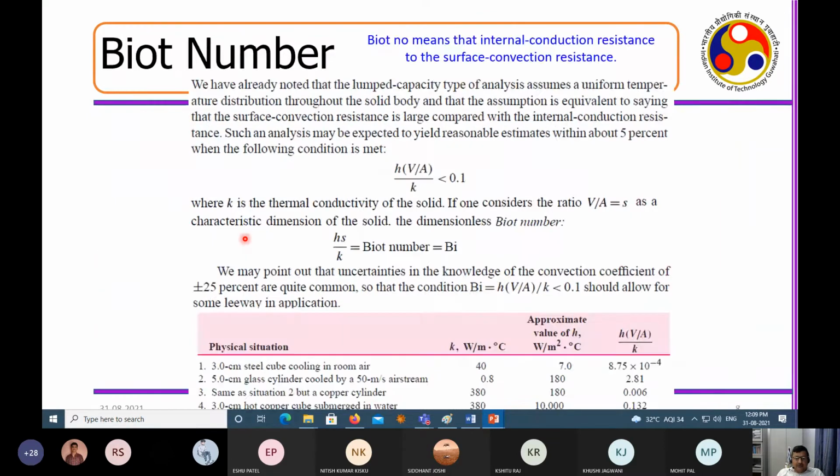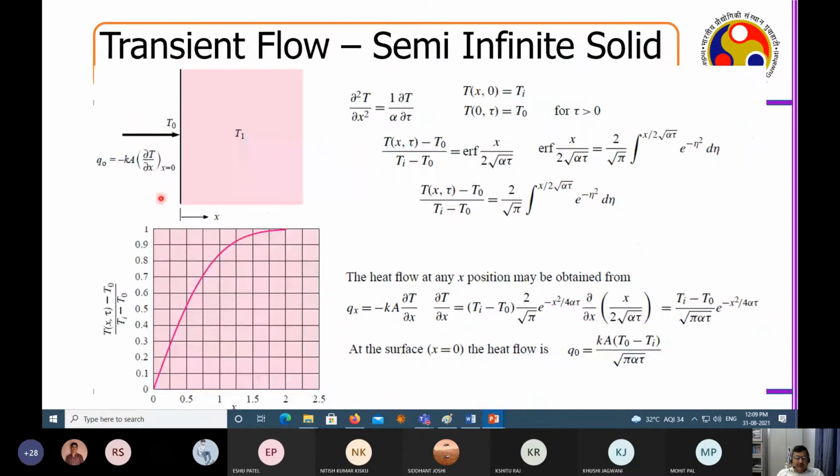Whereas, when you define heat flux, say suppose heat flux equal to 0, that means it's an adiabatic system. So different types of boundary conditions. Say, suppose you have put insulation, right? What is the boundary condition here? You will put a heat flux boundary condition, heat flux to be 0, and that is nothing but a Neumann boundary condition. So we talked about 3 different types of boundary condition: Dirichlet, Neumann, and Robin boundary condition, and we have shown what their architecture is.